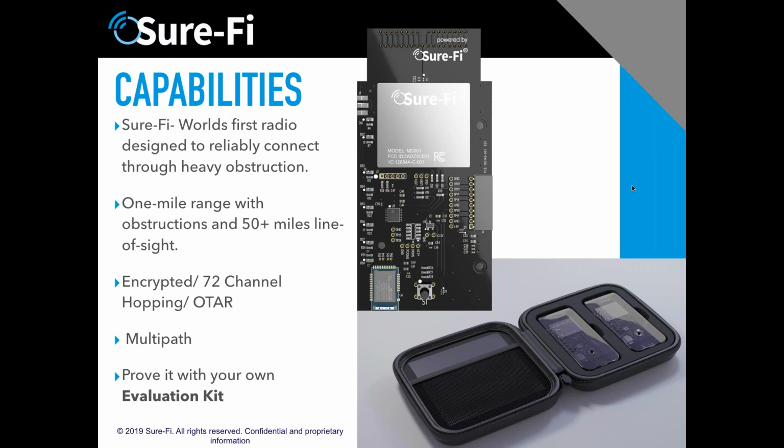Physical interfaces, he asked: RS-232, RS-485. Of course, there are adapters that can go to different things. I've tried it with an Ethernet cable, but you have to make sure it's not sending a local area network, which would be too much for the radio to send. But 232 and 485 within reasonable ranges work for the radio.